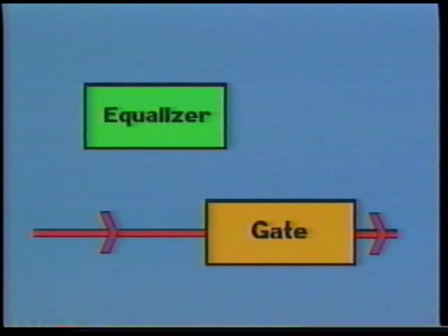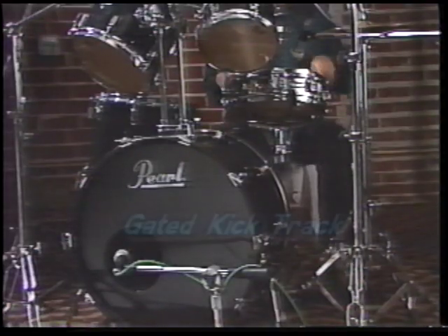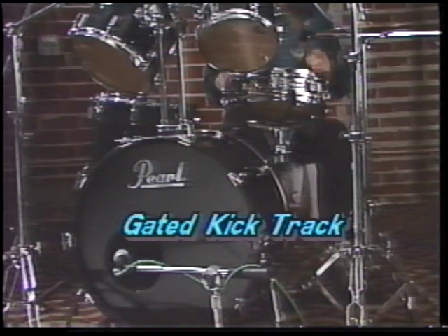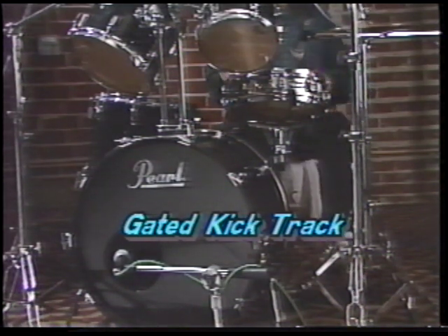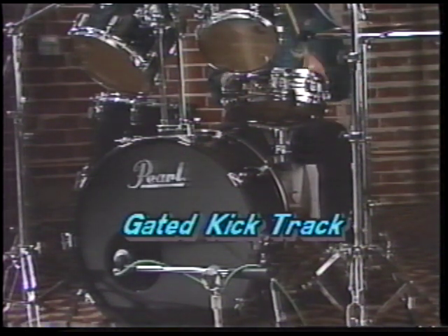Let the kick track go through the gate as it normally would, but also feed it to an equalizer. Set this equalizer to boost the kick drum attack frequencies and at the same time to tune out any sounds related to the snare. This signal will sound terrible, but since it isn't heard, it doesn't matter. The output of the equalizer is connected to the key input, which controls the kick drum's gate. The result is the gate opens on only the kick drum, and the kick drum's EQ can be adjusted for the best sound for the kick drum without any regard to the leakage from the snare.